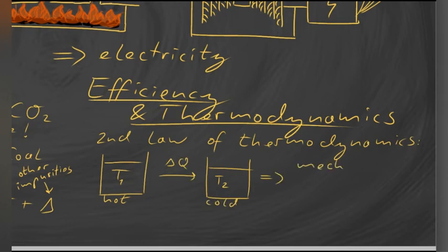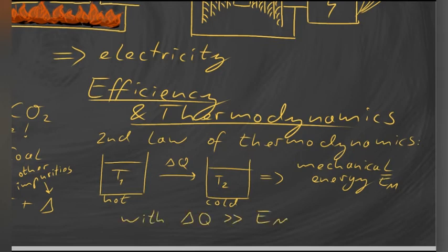The fraction of the heat released into a cooler medium must be equal or larger than the ratio of the absolute temperatures of the cooling system, which is the environment in this case, and the heat source, which is the combustion furnace. Raising the temperature of the furnace will dramatically improve the efficiency.